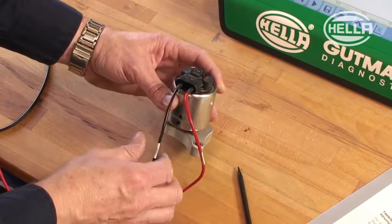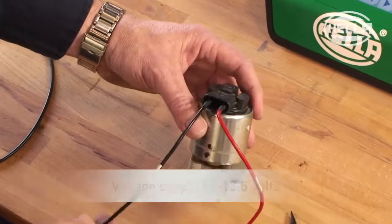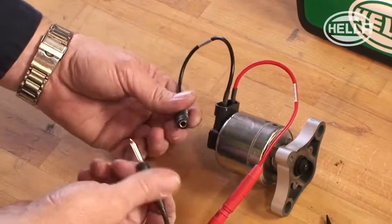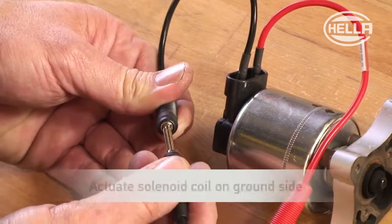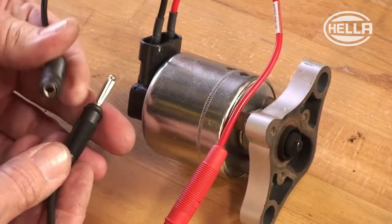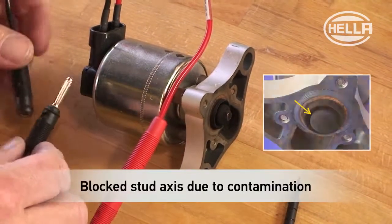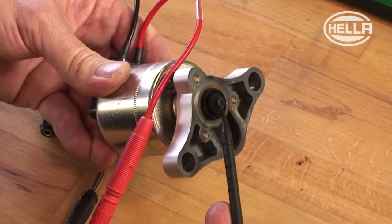For this check, connect the solenoid coil to a voltage supply with 12 to 13.5 volts. Connect contact pin E to the positive battery. Contact pin A is now connected to ground at short intervals via a cable. This actuates the solenoid coil on the ground side and checks the function of the valve stud. The valve must operate audibly and should open trouble-free. In this case, heavy contamination has blocked the stud axis, thus causing the EGR valve to fail.